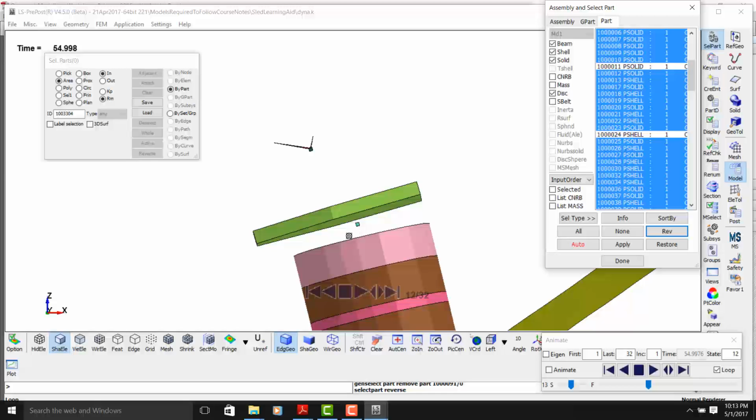The negative neck moment, which is so dangerous, is measured at this bolt. But unfortunately, if you check the real dummy, because there is a bolt going through this point, they cannot place a load cell there. They place the load cell 0.7 inches above this bolt, and it will be somewhere here. The load cell is here.